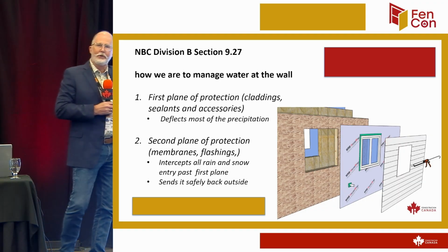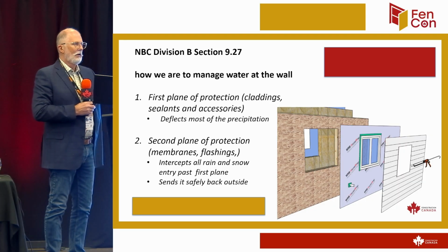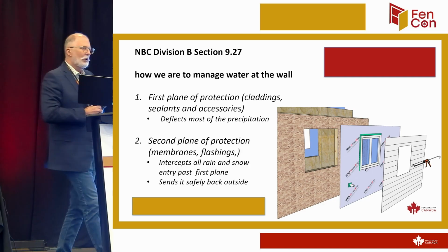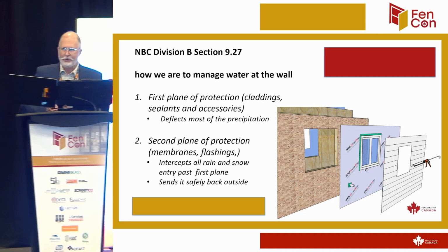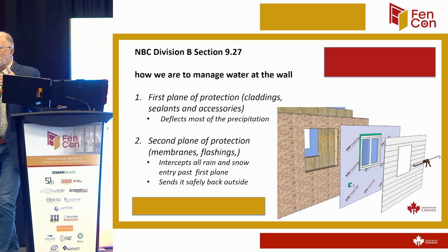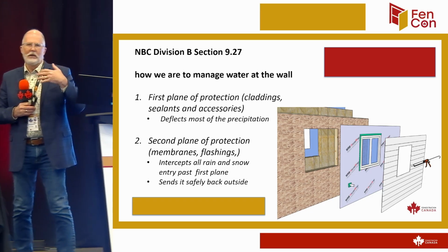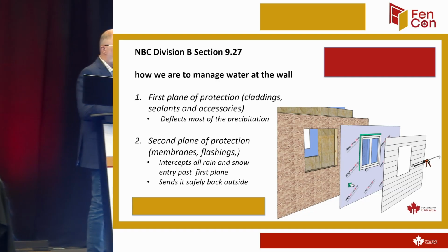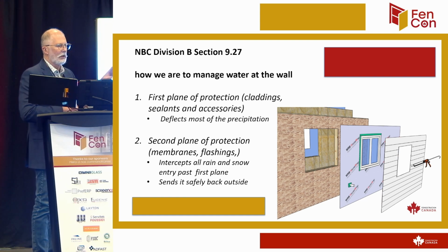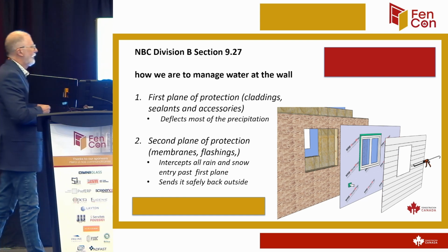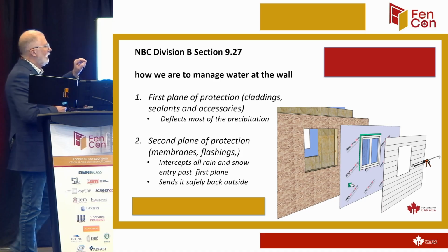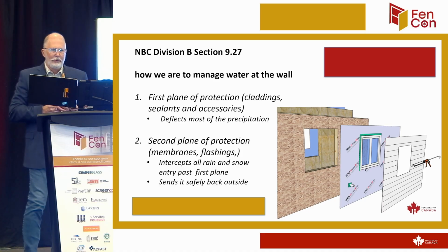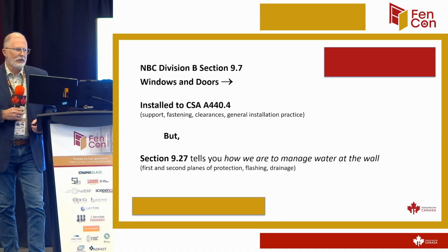So it all comes down to how much water can get back there versus how much that can allow to escape. And that's where we run into problems with things like manufactured stone or stucco or materials like that, because we let more in than can get out. Vinyl siding, almost a perfect cladding because it lets tons of moisture out, lets tons of air blow through it, dries it out very quickly. So it really comes down to the safety factor in how we get water in and how we get water out. So those are the 2 main points that the building code talks about.